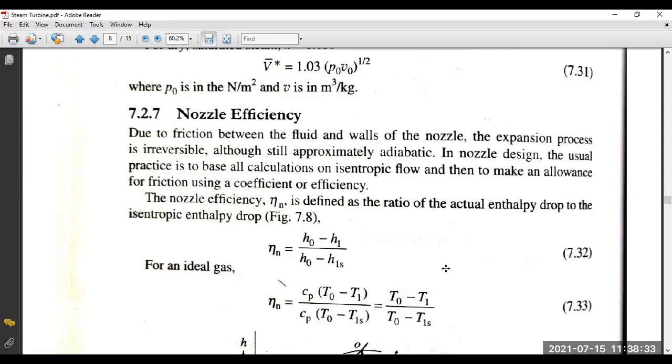The process is isentropic, means no heat transfer takes place and entropy is not changing, so the heat content or enthalpy H more or less remains the same as it was initially. Isentropic stagnation means a certain flowing fluid with a known incoming enthalpy and speed is suddenly brought to rest adiabatically, in a steady flow adiabatic and zero work output device.